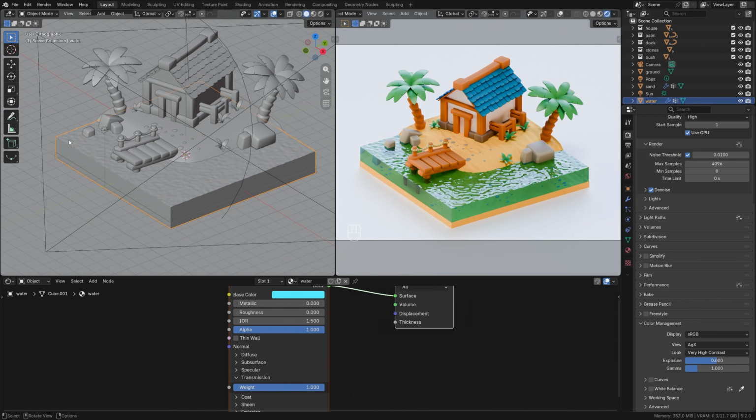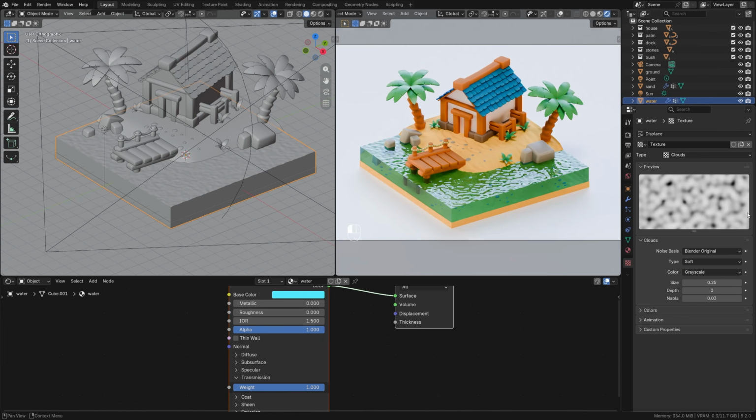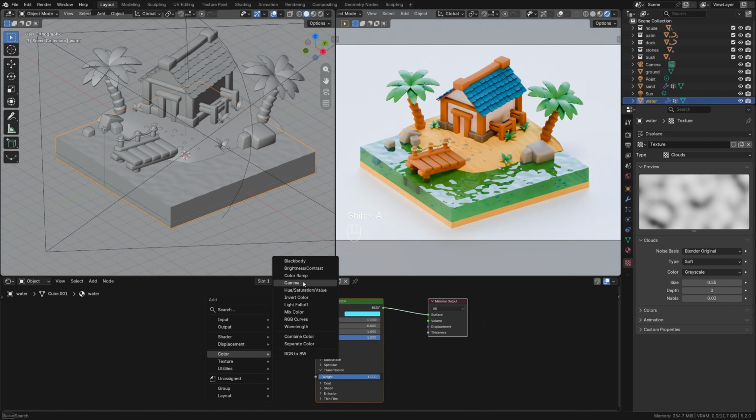Now we switch to water. First, you can remove the waves a little for the Displace modifier. Switch to the Textures tab, and here raise size to a value of 0.5. Waves will become bigger, and there won't be as many of them as there were before this. You can, well, here to each their own taste, adjust how you like it more, and you can refine the material. We add the Color Ramp node.